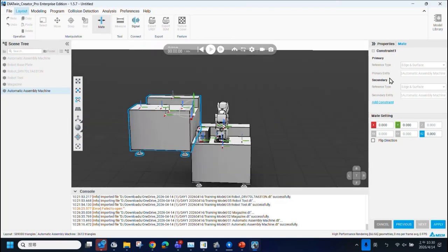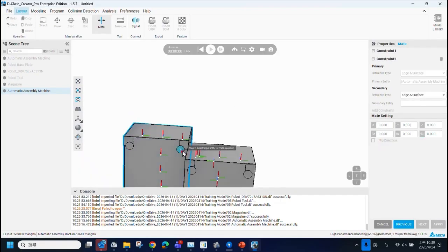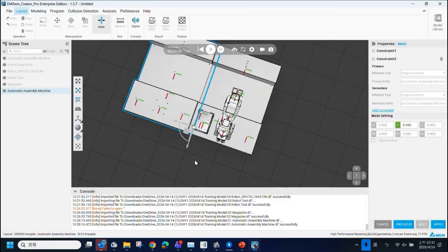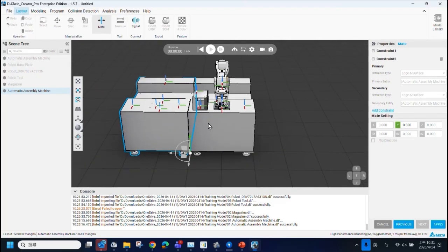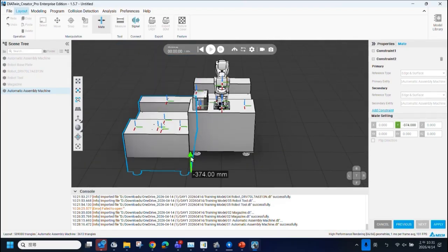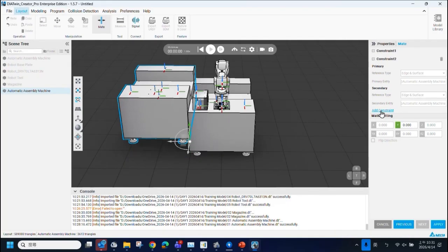Okay, and then if I want to have this constraint, maybe I'll add another. Maybe I add constraint. Maybe I'll press the end surfaces, and here also the end surfaces. You can see now these two frames will be combined properly. And finally there's only the last direction left, right? So actually you can just adjust it manually or also add a constraint.